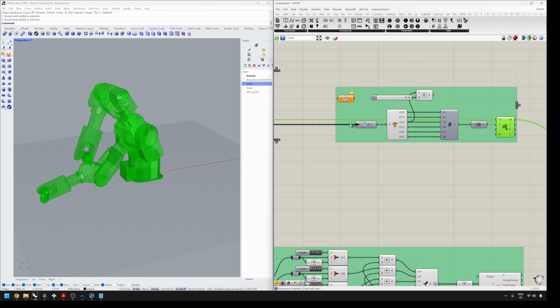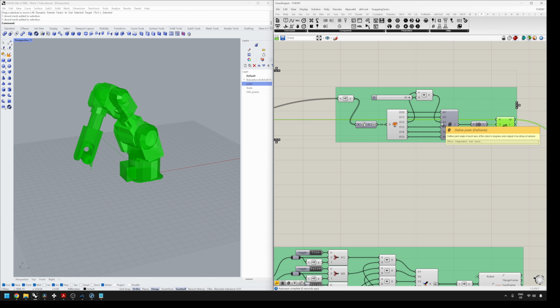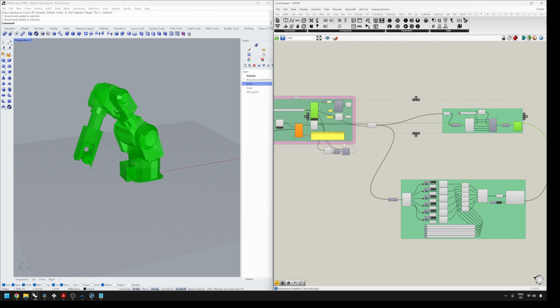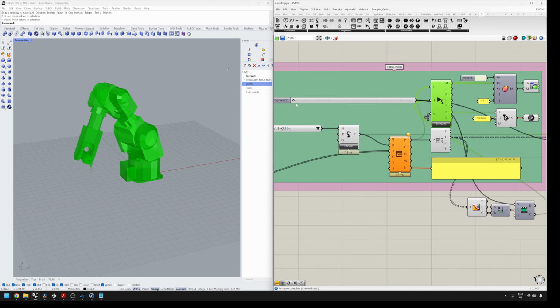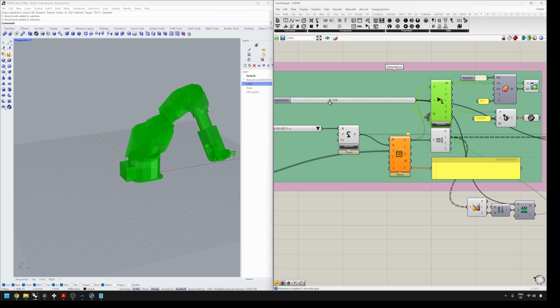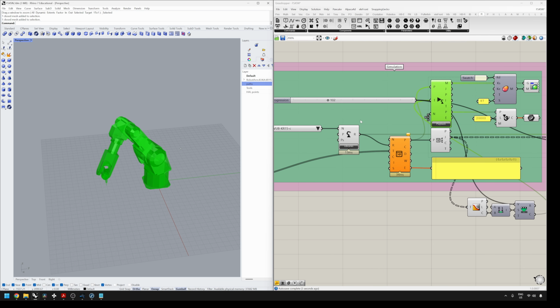For the robot plugin, flipping the signs of the joint values made the program and the forward kinematics of the robot align, except for joint 3, which also required an additional 90-degree offset. This may be related to RobotDK's minus 90-degree joint 3 offset and could indicate that the systems are using different sign and 0 position conventions.